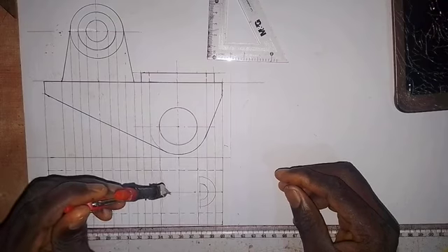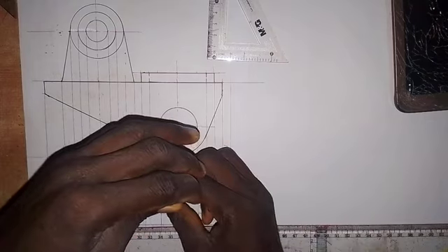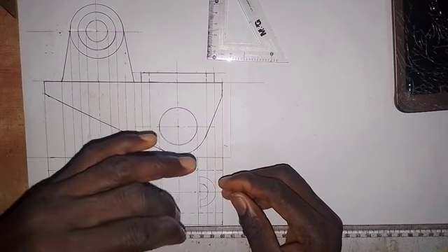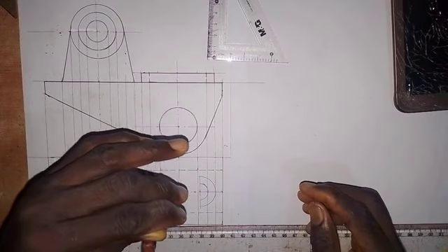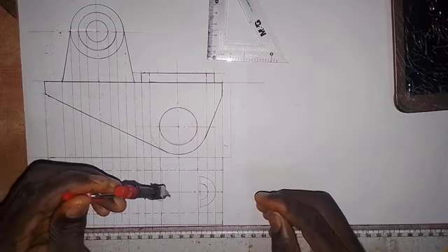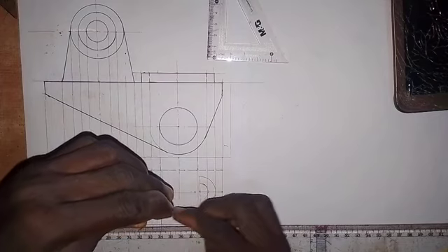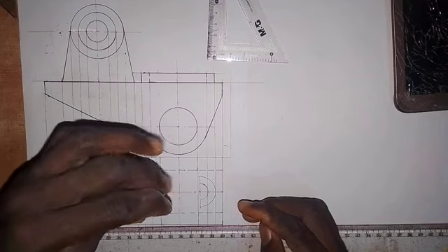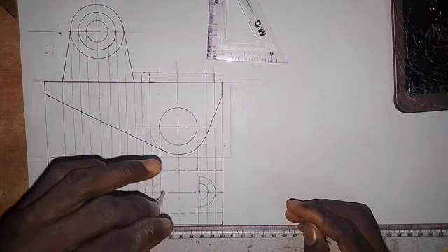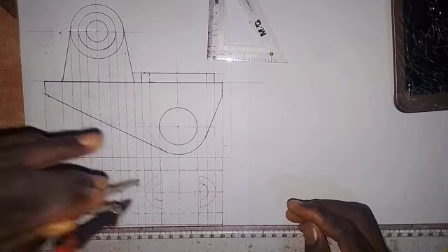Then coming to this point here, I will also draw from here to this side for the small one. Now we also do the same thing here, very carefully. Then I will draw the big one from here. So the big semicircle: I will extend the compass to this point, and turn it to this side, and also turn this one to this side here, so we have this touching this line. Alright, so we have this now.